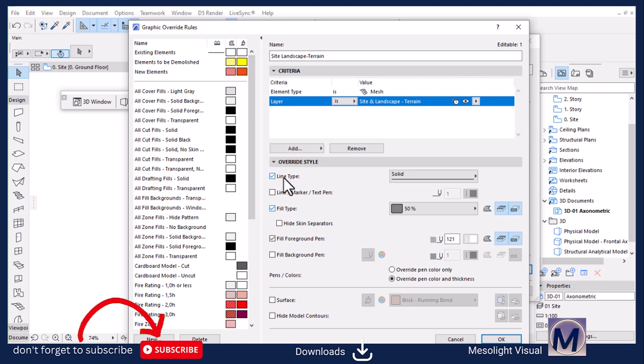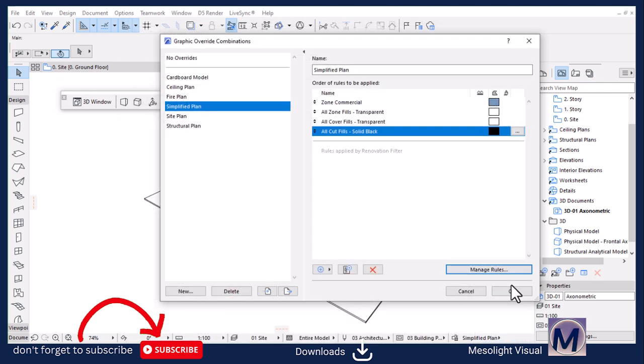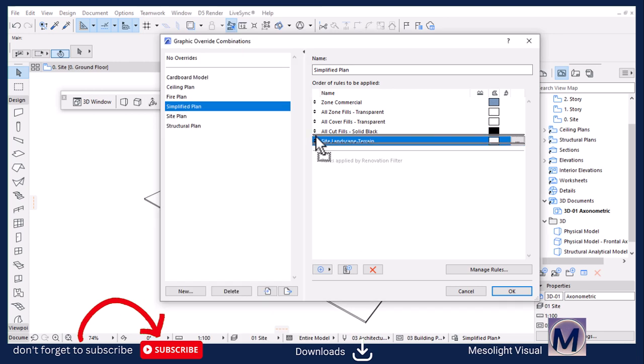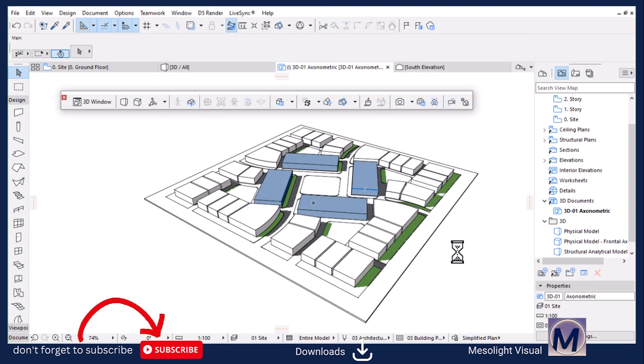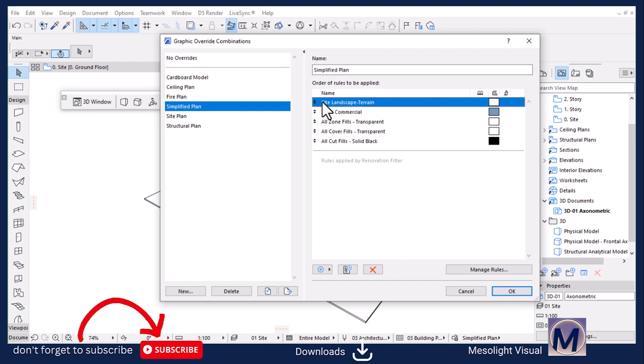Then we can also override the line. No, not the line, the line marker, to something gray. 0.13 millimeters is fine. Then hit OK. If we add that newly created rule and push it to the top like that, then hit OK, nothing will change. Because why? The foundation, the master of all, which is all cut fields, is solid black. We didn't exclude the newly created landscape terrain layer from it.